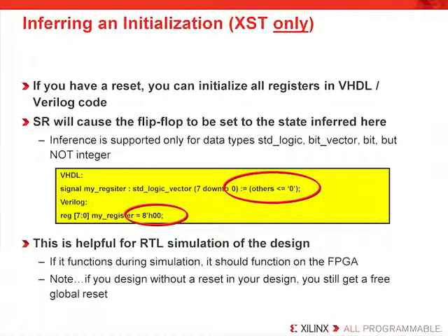If you do not code this, then you will have X's on your counter, counting +1, and all you will see during simulation is an X counter. But if you code in this way, it will start with a known value, in this case 0. So this is mandatory if your design has no reset on the circuit. Now, inferring an initial value only works for data types of standard logic, bit vector, and bit, but does not work for integer types. And note that this inference is currently not supported for Spartan 6 devices, but will be.